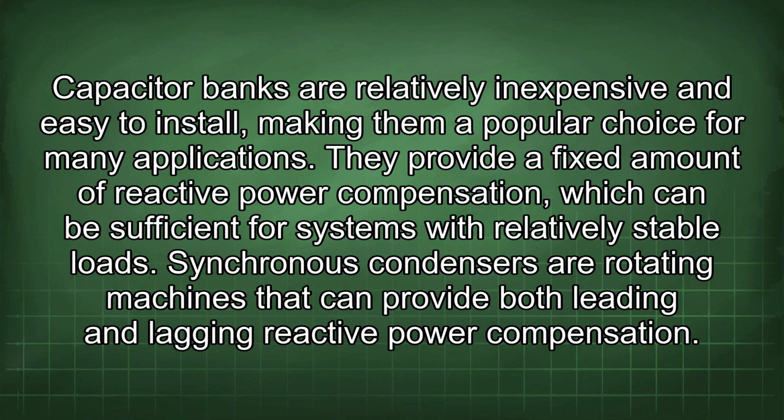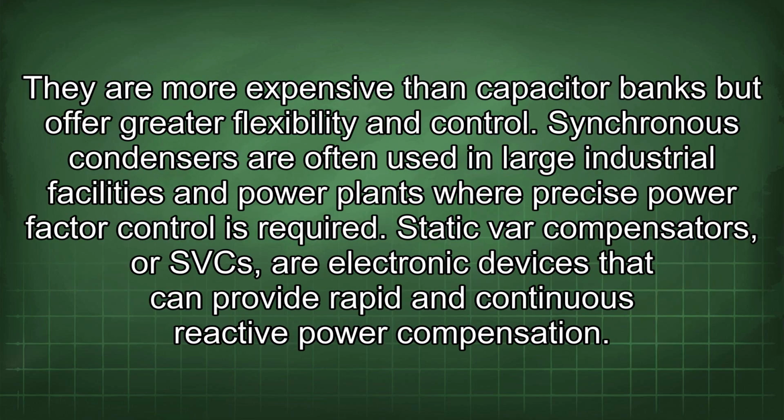Synchronous condensers are rotating machines that can provide both leading and lagging reactive power compensation. They are more expensive than capacitor banks but offer greater flexibility and control. Synchronous condensers are often used in large industrial facilities and power plants where precise power factor control is required.